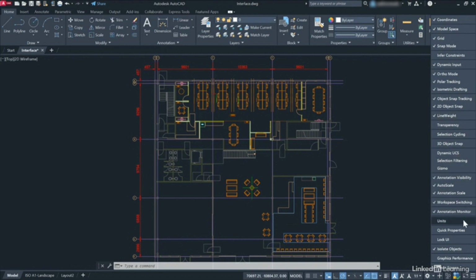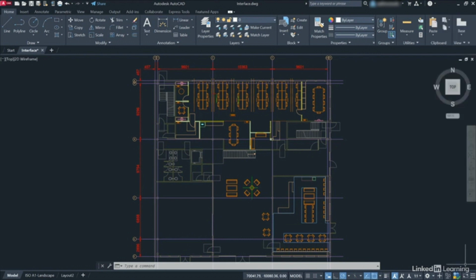screen. So we come down to the little 3 bars again here, like so. Click on the 3 bars. That closes the customization menu. So you'll notice now, when I move the crosshair around in the AutoCAD drawing, you can see my coordinates here are displaying. I can right click there and I can show specific, geographic, absolute or relative coordinates if I want to. I'll hit escape there just to lose that little menu.